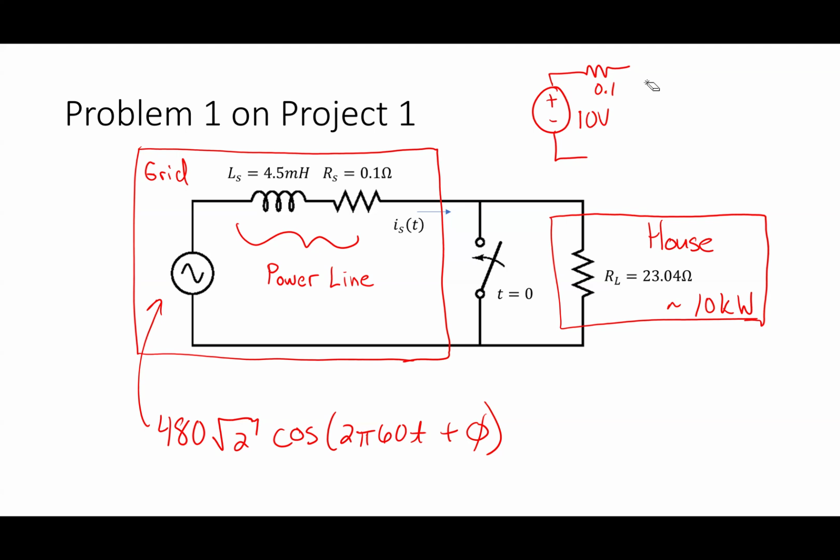So obviously, in the power grid, we have to have protection in the system. You don't want a line short circuited to ground and the current just pumping around, right? That would be bad. So what we do is we have a circuit breaker, which would be somewhere over here, basically a switch that will open up whenever what we call a fault happens. So I got to choose that circuit breaker carefully, right? And when I say choose it carefully, what do you mean by that?